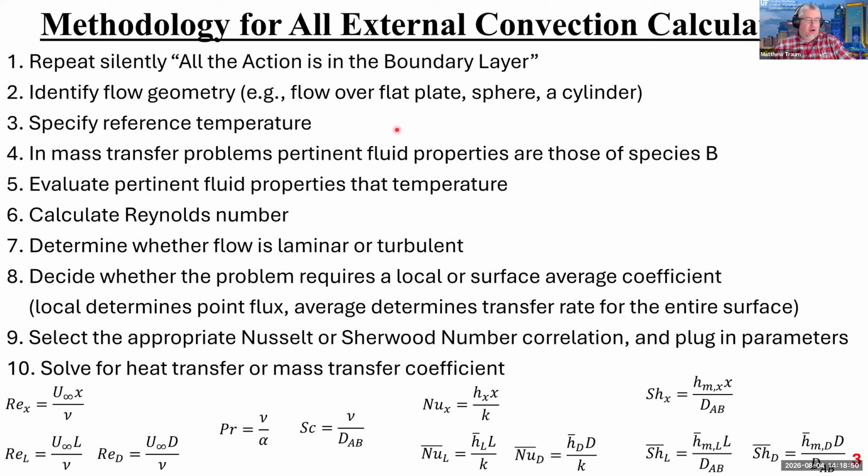One of the really important outcomes from what we're going to talk about today is the underlying equation for convective heat transfer in a boundary layer is also the underlying equation for mass transfer, right? So when I say mass transfer, I mean like the diffusion of particles in a gas. So like humidity, for example, water vapor and air. And so even though this is a heat transfer class, it turns out that we basically get 2 for 1. So one solution for free, which is if you solve the heat transfer problem, you're also inadvertently getting the solution to the mass transfer problem.